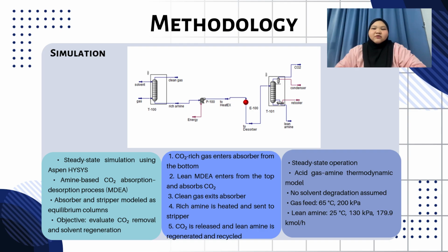This slide presents the key results obtained from the Aspen simulation of the amine-based CO2 absorption-desorption system. The simulation showed that the MDEA solvent effectively removes CO2 from the inlet gas stream. Based on the material balance calculation between the inlet gas and the treated gas stream, the overall CO2 removal efficiency was approximately 82%, indicating successful absorption performance in the absorber column.